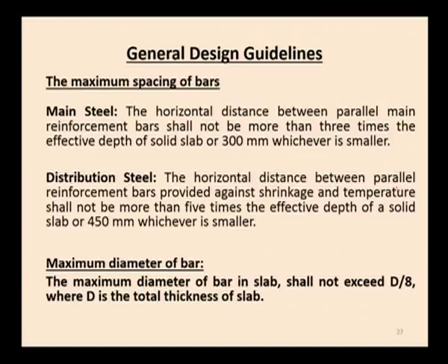So, in the case of main reinforcement, the spacing should not exceed 3 into depth of the slab or 300 mm, whichever is less. In the case of distribution reinforcement, the spacing of reinforcement should not exceed 5 into depth of the slab or 450 mm, whichever is less.